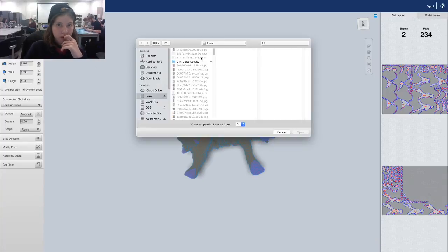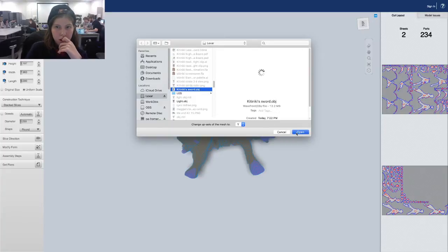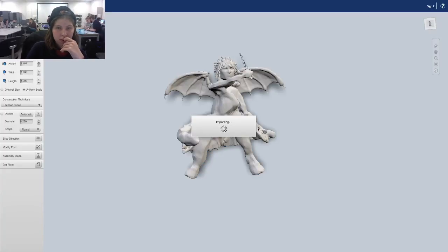Set up a sketch plane looking that way and sketch the nose with the tip of the spline, and then cut extrude it into the body. Try the spline, sketch the spline. Go around the back. Just add points and sketch the head of this.